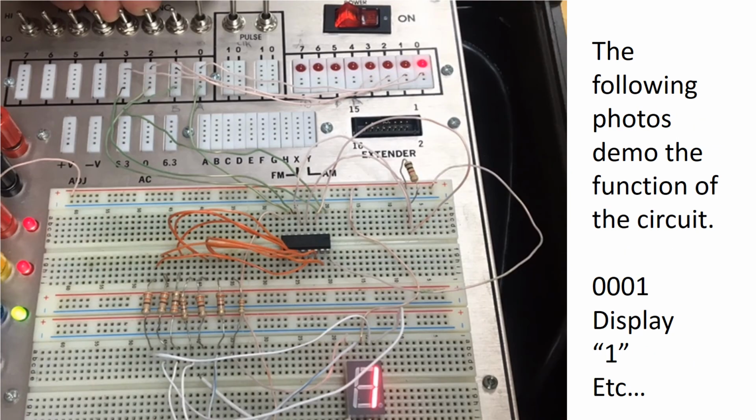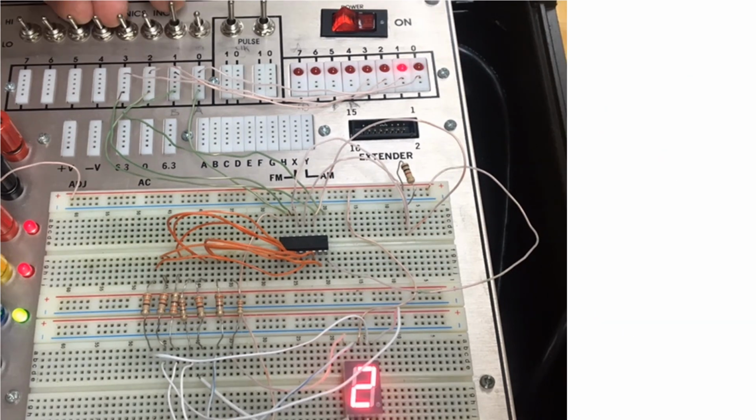So the following photos demonstrate the function of the circuit. You can see here the switches are set to 0001, or the number 1. You can see the LED lights at the top are showing 0001, that the binary number 1 is indeed being provided electrically. And then at the bottom of the screen, you can see the 7-segment display correctly draws the picture of the number 1. Here's the number 2 with the second switch up and the first switch down. So it's a binary 0010 for the number 2.